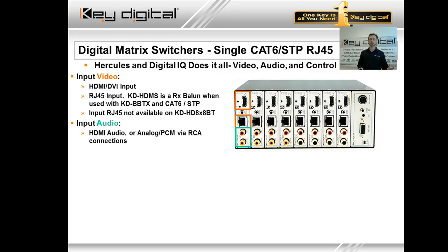When the source is given a handshake that says, hey, you have the green light for your Dolby, for example, both HDMI video and audio are on that HDMI connection, and now you've got Dolby coming from that source and into that HDMI input. But imagine in that very same system, you have a display on the wall, and that display, of course, is only able to deliver to you 2-channel audio, and the majority of displays available in the industry today only support 2-channel audio.